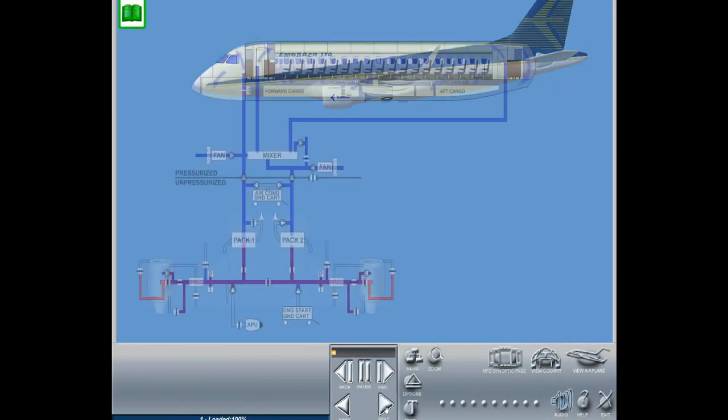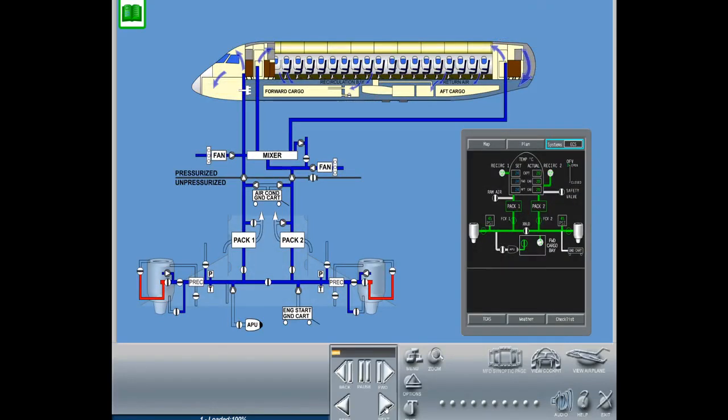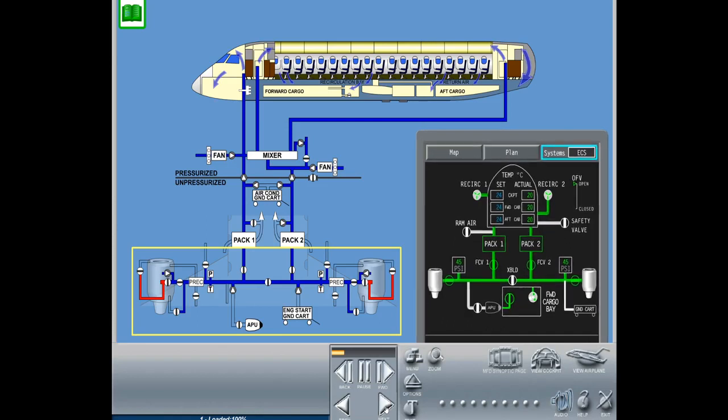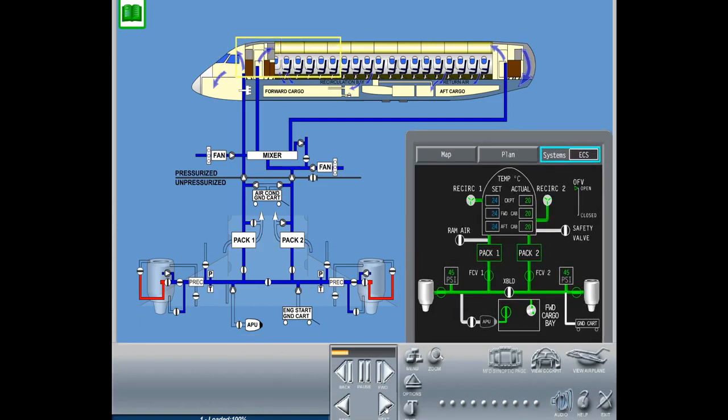The Environmental Control System, ECS, uses bleed air from the pneumatic system to provide air conditioning for the cockpit and cabin, filtered air recirculation, conditioned air supply for gaspers, and fan air cooling for avionics located in the electronic bays. Additionally, an emergency ram air ventilation system is provided for cockpit smoke removal. The cargo bay ventilation system provides adequate airflow to the forward cargo compartment.